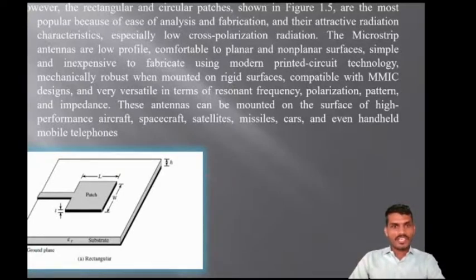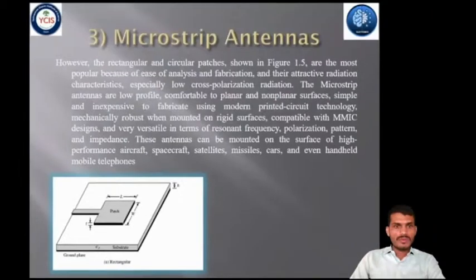This is a rectangular or square patch. This is a rectangular square patch which is placed onto the substrate, which is connected to the ground plane, and this is the patch with T as the thickness, W is the width of that particular patch, L is the length of that particular patch, and H is the height of that substrate.